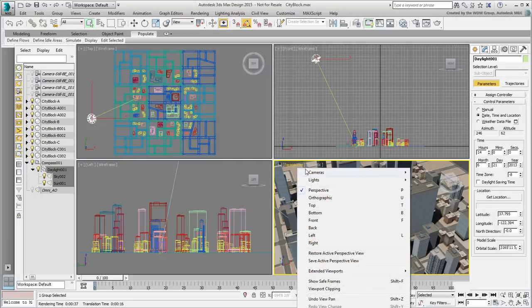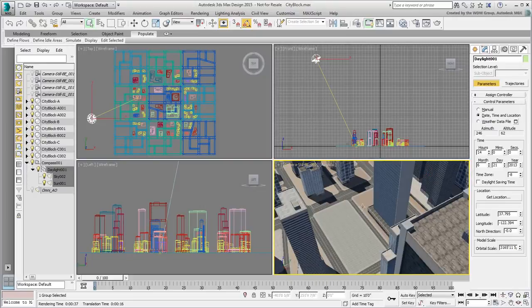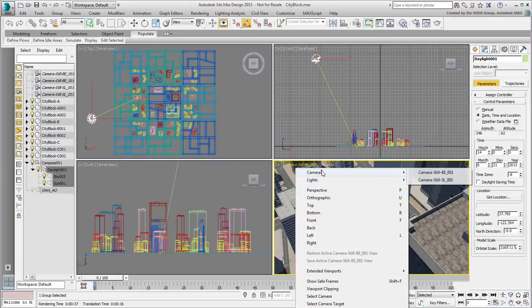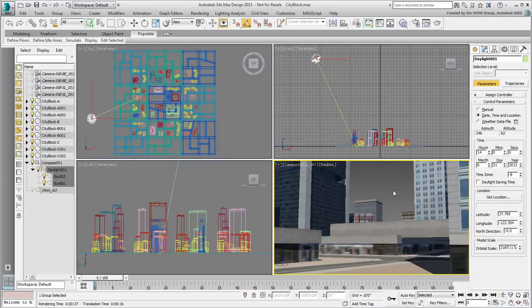Also, there are a couple of camera shots already defined, and you will be creating and animating others later on. For that reason, you don't absolutely need to include cameras coming from Revit either. Therefore, you will import and link the museum you worked on previously, but you will use the link preset you created in the last movie. This way you ensure you bring in all geometry, but discard any cameras or daylight systems that are stored in the FBX file.